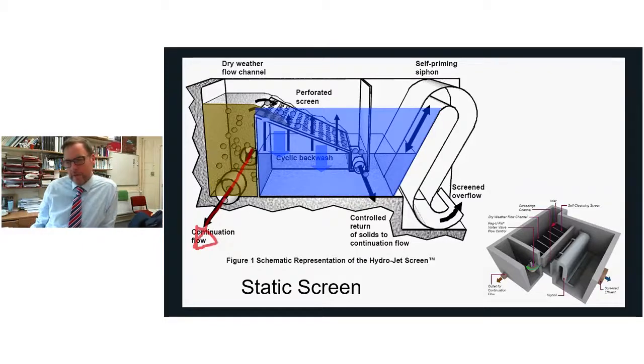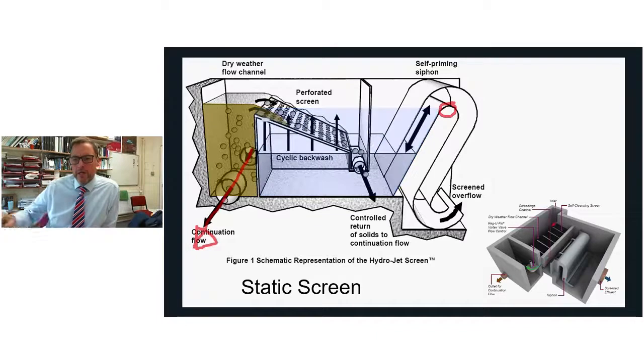Okay, and eventually it reaches a point where this part here, the siphon, is activated, because once it gets over there, a siphon's formed. So there's the flotation of the solid particles. That's what the brown arrow is for. We've then got the siphon filling, and then once that siphon fills, that draws down the flow in this container quite quickly. Okay, and then the process starts again.